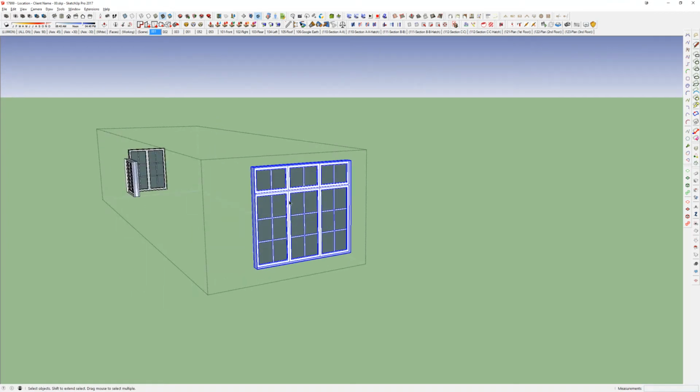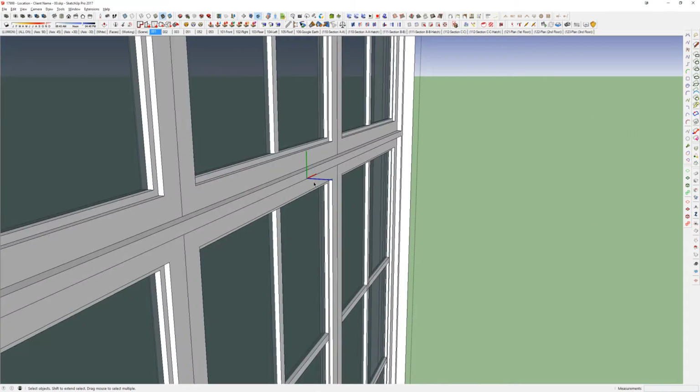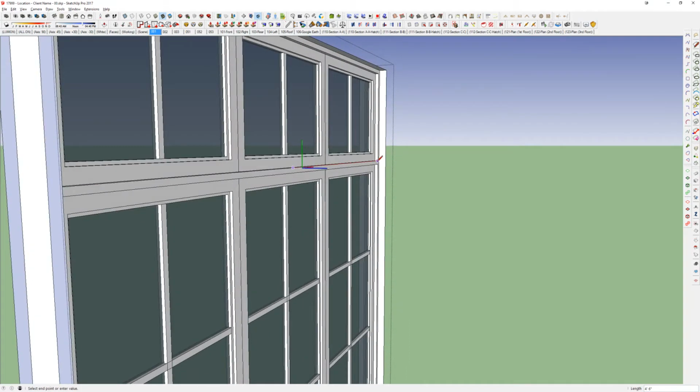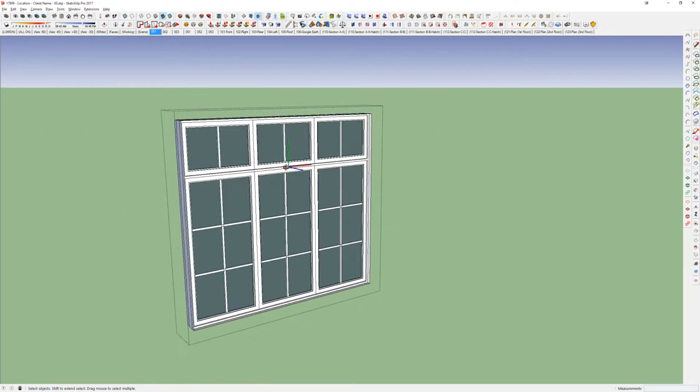And to get back to one of Felicia, one of your questions in the very beginning, as far as the importance of the origin point that I was talking about earlier, the reason why this reloaded properly is this actually has the origin point right here in the top middle. Because essentially this is the same window as the other one, it's just from this point up is different. So it's reloading by this insertion point, and that's why it reloads properly.